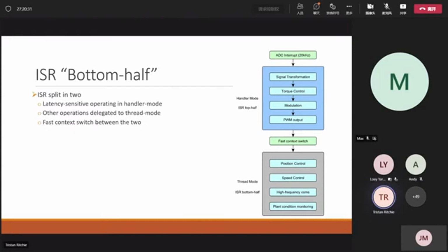Implementing this in RT-Thread is perhaps a little counterintuitive, as RT-Thread is supposed to be a hard real-time operating system. And by bypassing the scheduler in this way, we've effectively created a soft real-time kernel, as this bottom half ISR thread cannot be preempted by another regular thread.